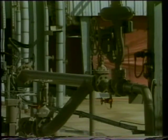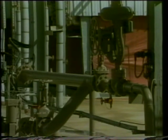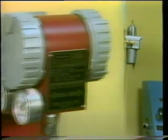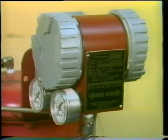It's also necessary to identify any auxiliary devices that are required. For example, the application may require a manual override that can be provided by a hand wheel, or a limit stop to prevent the valve from being opened beyond some predetermined limit, or a positioner to provide the required degree of control. Another auxiliary device is a transducer that converts an electrical control signal to a pneumatic control signal.